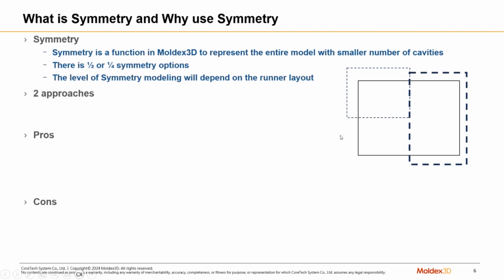And if all the quadrants of the mold have a symmetrical runner design and symmetrical parts, then you can just run a quarter of the mold and get to your answer. If you are troubleshooting any issues inside the mold, like shrinkage, warpage, or air traps, things like that, you can get the answer for your complete mold by just running a section of the mold, right?